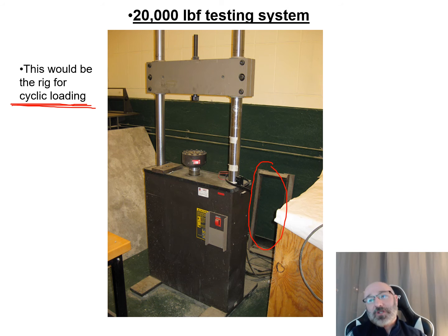When we put the snowboards in 3-point bending to simulate a riding scenario, we wanted to test the cores. We were comparing different types of cores for the Burton snowboards, and we wanted to put them in cyclic loading to simulate X number of hours of riding, X days of riding, to see when the fibers in the core were going to break down and snap, and you'd lose some of the camber. So we wanted to use cyclic loading.